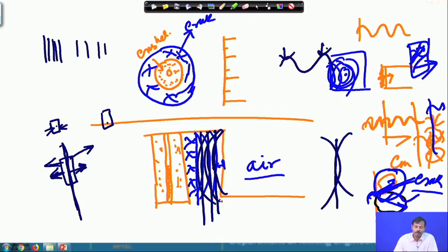As the shock energy is released from here first, it immediately cracks the crushed zone, then the shearing zone, then goes up to this, then returns back from here, creating these tensile cracks prior to release of the gas energy.